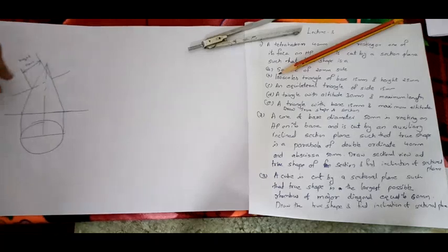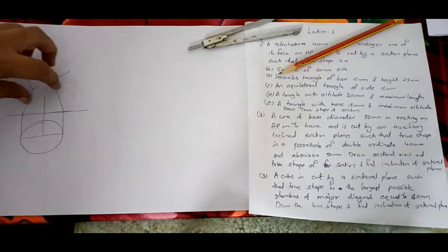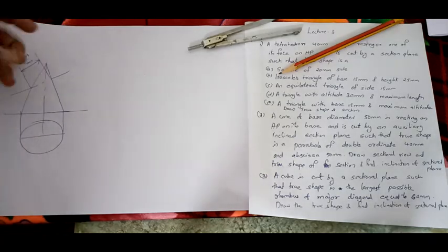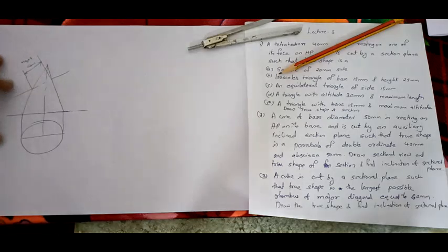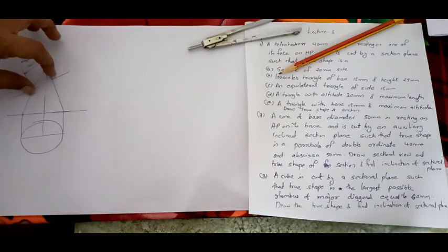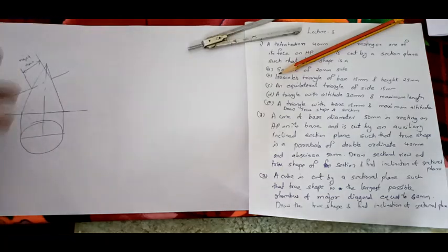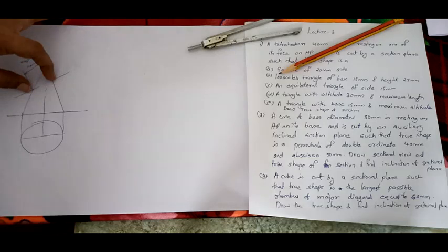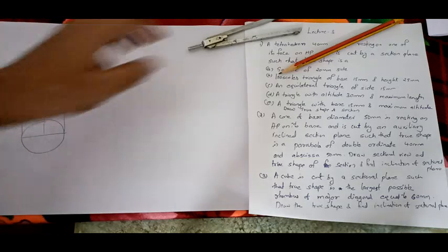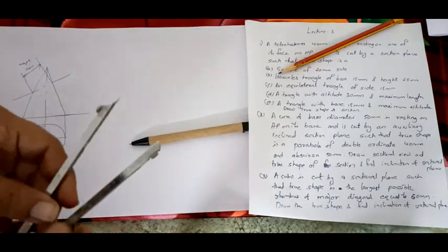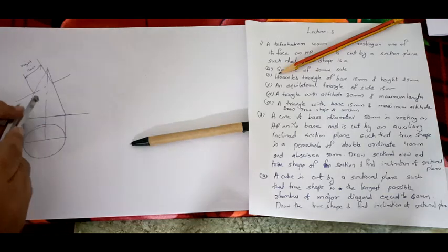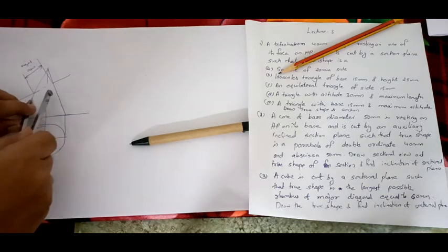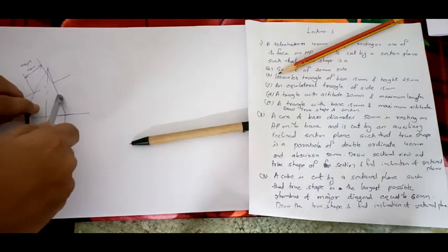Infinite number of ellipses you can take from any point. You can cut from any point to another section, right? So 20 mm means if you start from here, it may cut here. It may start from here, and it may cut here. So infinite number of ellipses you can obtain with major axis equal to something. You can start from any point. So they have given 40 mm. Take 40 mm on the compass.